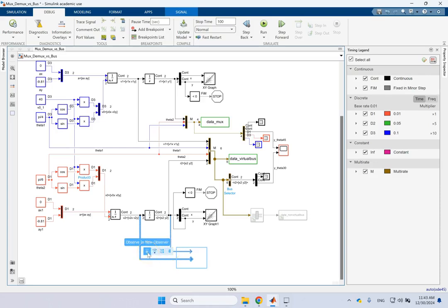It allows you to put it in Observer, to basically log it so you can look at it in Data Inspector. And look here, it allows you to auto route the lines which you don't want. This last one is a bus creator. So you just click there, boom, the bus is there.